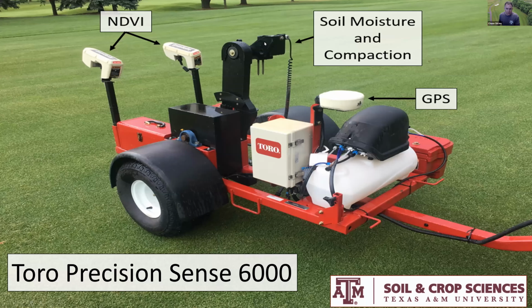It has a similar sensor to the soil moisture sensors in the handheld devices, a little bit different, but I won't go into detail on that. And then it has a load cell sensor to measure the amount of force it takes to penetrate. That'll give you the compaction reading, and then it also measures salinity.